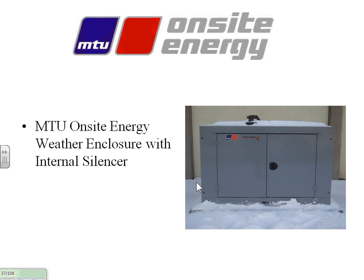And one thing I should tell you about a generator set, any generator set, it's not like your car. You've got a radiator and a fan, but they're not the same. On a car, you've got a sucker type fan to where it comes in through the radiator in the front typically. The cooling air moves over the engine and goes down by the firewall, right? Generator sets just sit there.